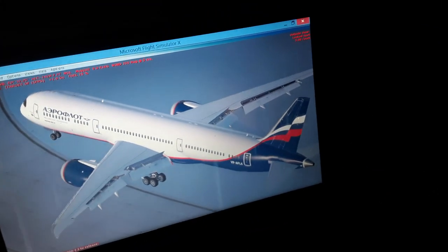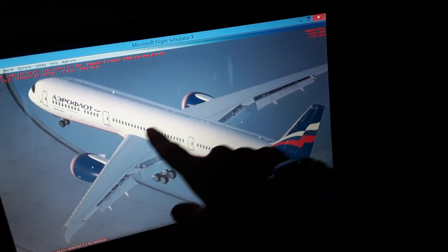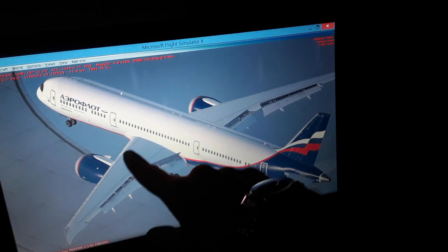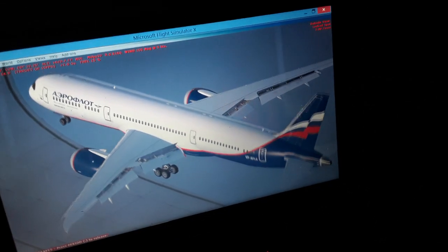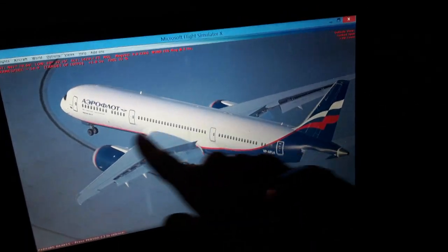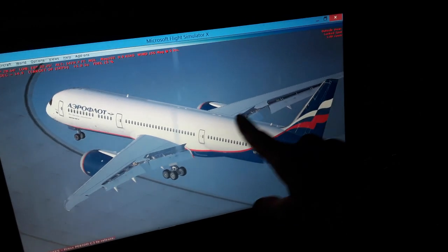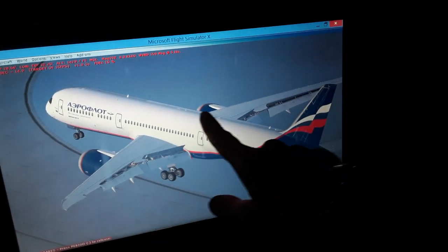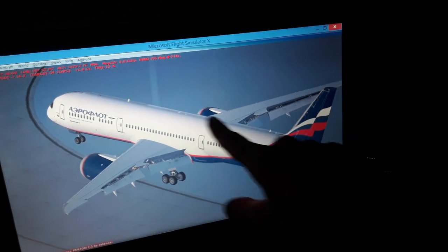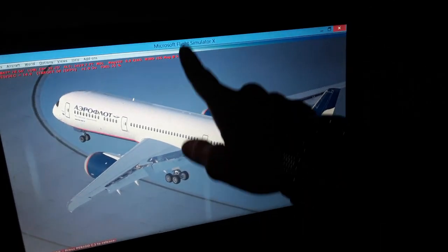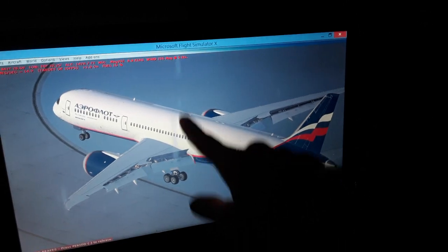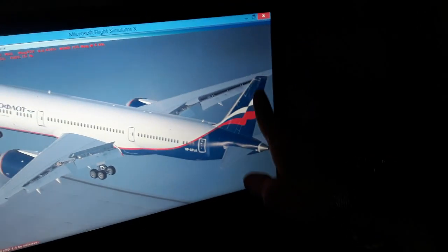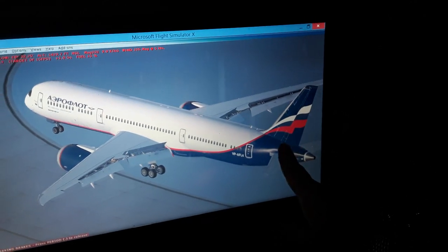We have also the mean aerodynamic chord. We have, as I told you, the fuel, the center, left and right wing fuel tank. So we have the center of gravity located where the mean aerodynamic chord is in the forward wings over here. So this is the section, the forward wings, and you have the center of gravity transverse the other axis of the aircraft. So through the center of gravity you have the rudder here, the vertical stabilizer.